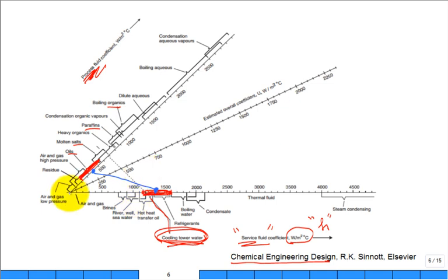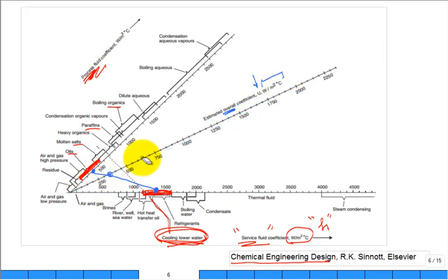It's where it crossed another line, which was our overall coefficient, capital U, in units of watts per meter squared. So it's like, oh, this one comes in, if I'm just trying to read it, there's 250, there's 500. Looks like it's the 350. See how they do that?